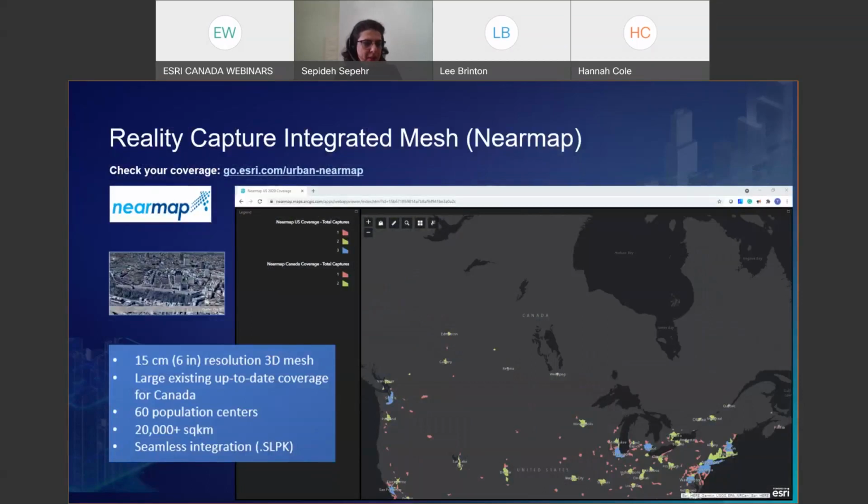Nearmap is a partner of Esri Canada who has provided textured mesh, point cloud, DEM, DSM, and high-resolution aerial imagery in Canada. For the Canadian user, they can make the mesh available as an offline delivery in SLPK format or online with an export capability to export the area you want. The point cloud is in the form of an LAS file with 3 bands and 44 points per square meter. Nearmap captures aerial imagery proactively with a methodical capture plan in Canada, so it's available immediately.